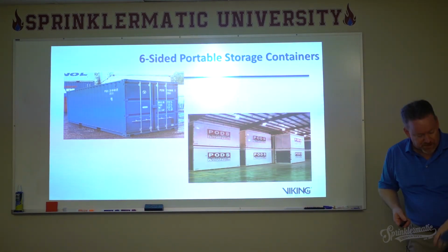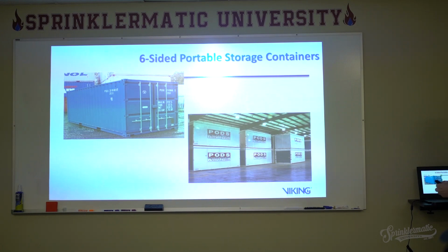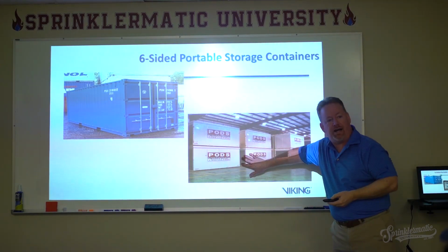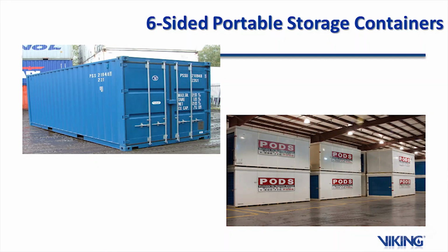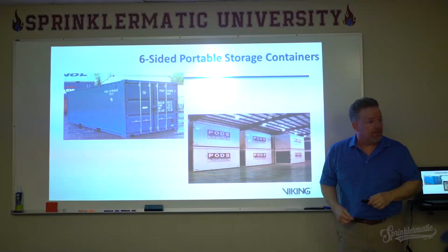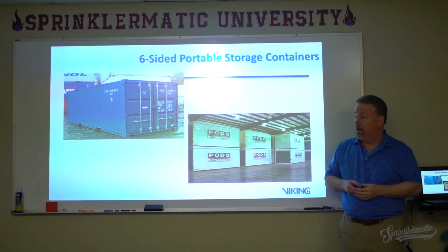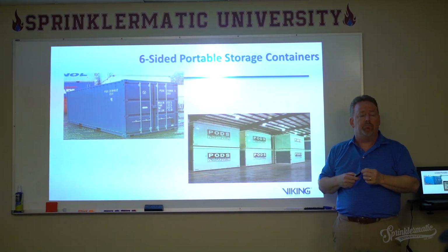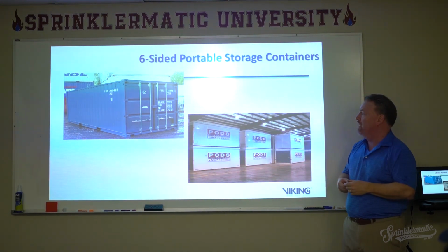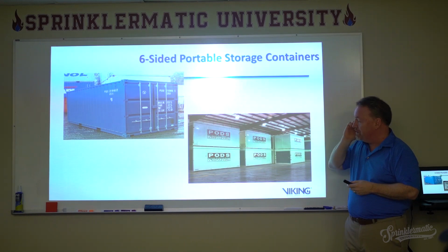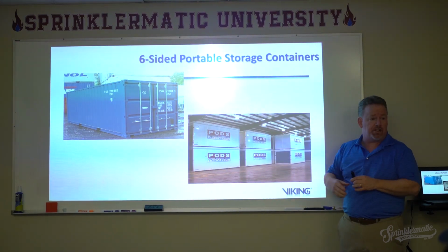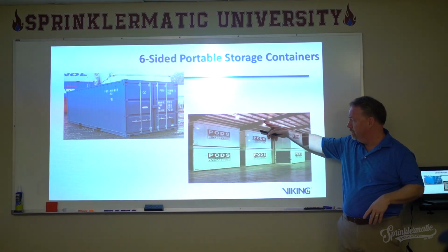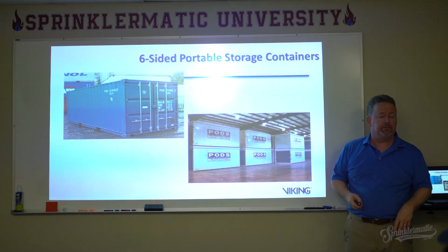Finally, and again, I promise this is finally, we've got 2 things left here. 6-sided portable storage containers, pods. How do we protect these? Don't know, okay? We really don't. When I asked the technical committee about this 7 years ago, they said, well, we just use ESFR sprinklers. We just spray the whole thing. All right, right down over the whole thing.